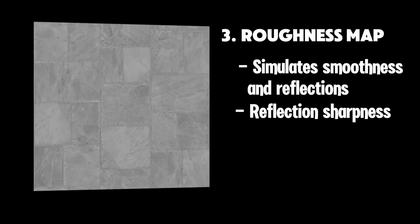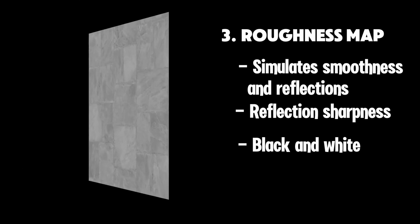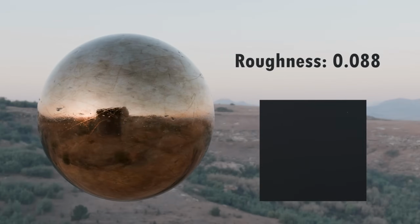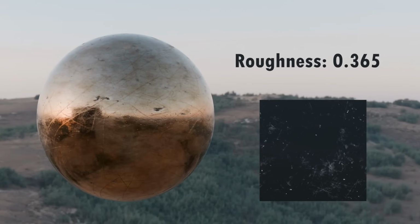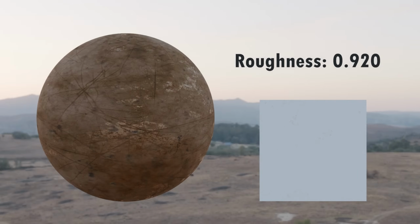Let's talk about how roughness works. The roughness map shows how rough or smooth the surface is. Besides that, this map also controls the sharpness of reflections on the surface from the environment. A rough surface scatters light in multiple directions, resulting in diffuse reflections and softer highlights, while a smooth surface reflects light more directly, creating sharp highlights and glossy reflections.